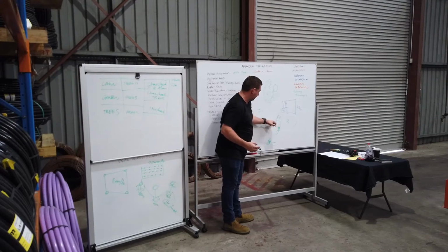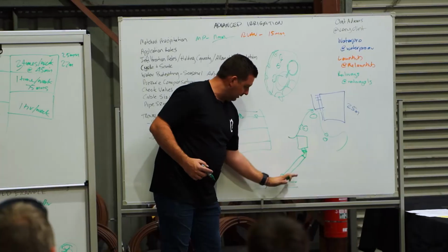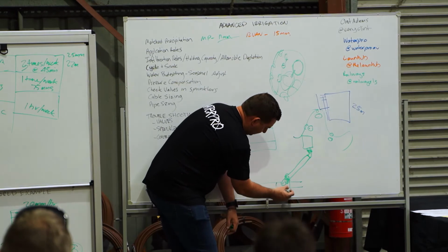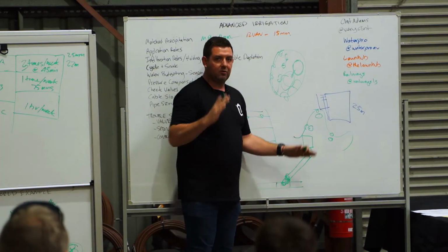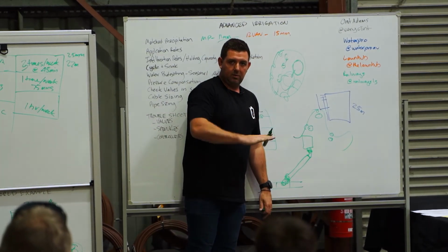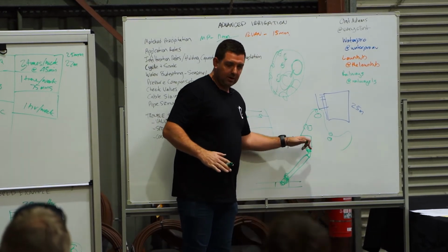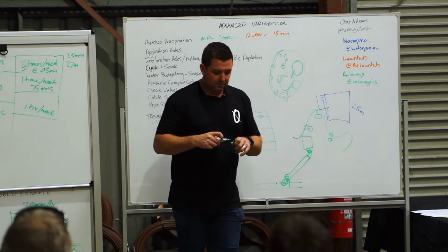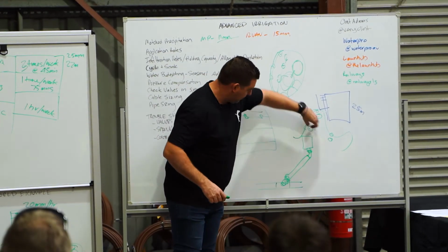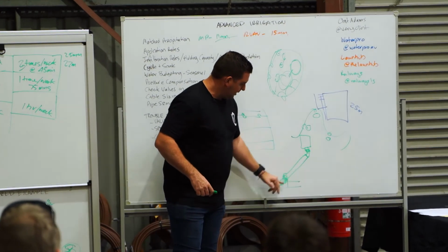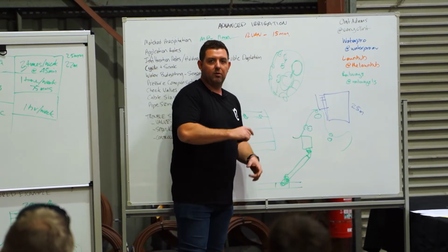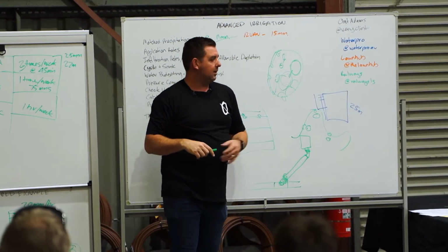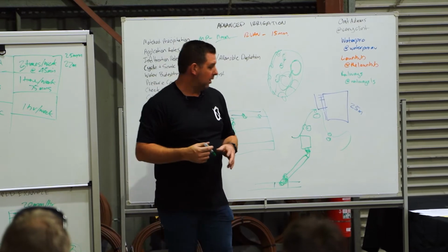So the idea is that if someone drives over that sprinkler, the riser, there's 2 elbows there and 1 there, and they sit in so that might be PVC, and if they drive over that sprinkler, it takes the load of the car rather than snapping or breaking the sprinkler. It can sometimes push the riser down, or if you need to adjust the sprinkler height up or down because it's been top dressed, you just dig around there and lift that up a little bit, rather than trying to unscrew the whole sprinkler and put those male-female adapters and just keep making the sprinkler higher and higher. I'll grab one before, I'm sure we have one here. I'll grab one and show you guys before you go.